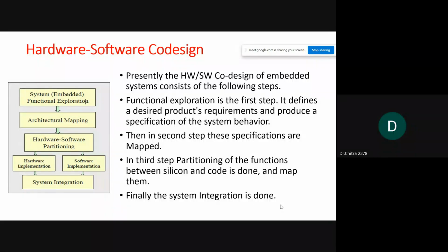For example, if you want to design a thermostat, that is our example. In our example, we need to read the sensor data, temperature sensor data. So definitely there must be a code to read the temperature sensor data. You should write a code to read this data from the port. This value should be connected with some port, and from that port you must read the value. For the port connection itself, you can use a microcontroller. In the microcontroller we are using the IO map concept. There are the memory map concept and the IO map concept. We can use the IO map concept.